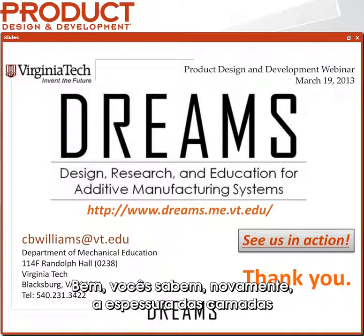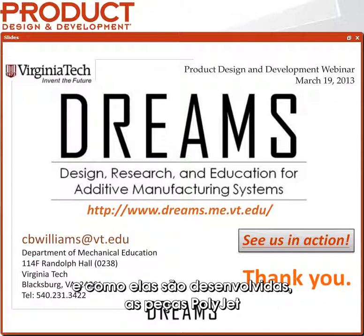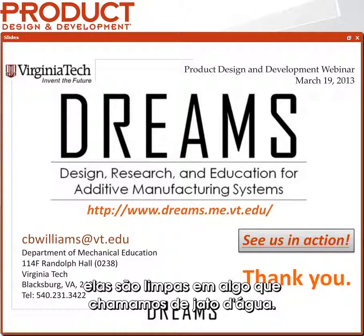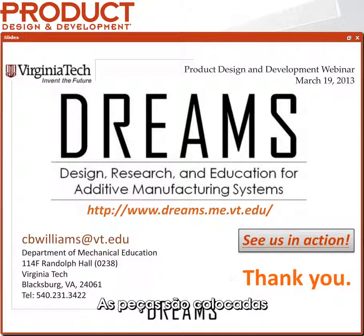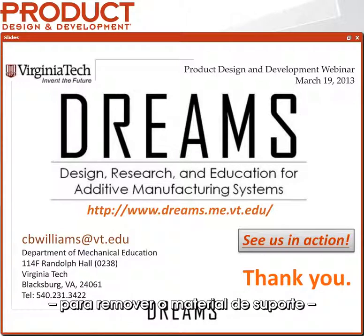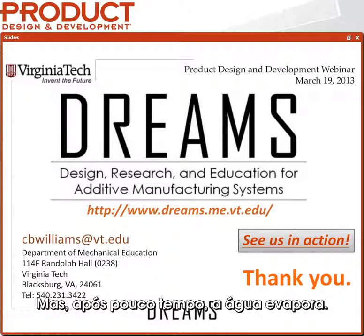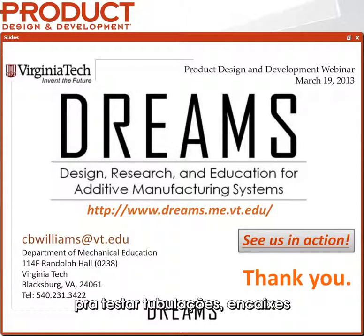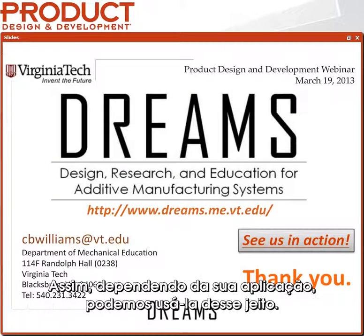Well, again, the layer thickness and how it's developed, the actual PolyJet parts, the way they're cleaned, you actually clean them in something called a water jet. So you put the parts into a water jet to remove the support material. It does absorb a little bit of the water, but over a little bit of time, that water is evaporated. We have lots of companies in the oil and gas industry that use it for testing of pipes and fixtures and things along those lines. So depending on your application, you can use it in that.